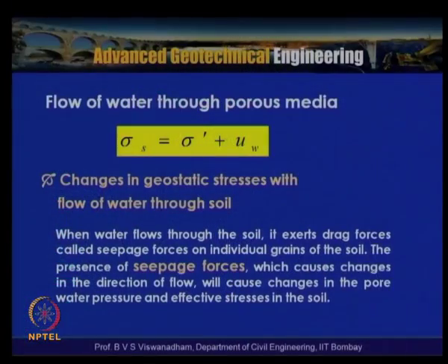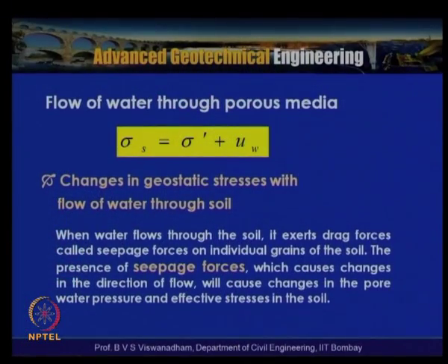And we actually have discussed that the total stress is nothing but the effective stress plus pore water pressure. We also have discussed this for a no-flow condition, that means there is no difference in head between two points under consideration. In that case, we say that hydrostatic pressures prevail.